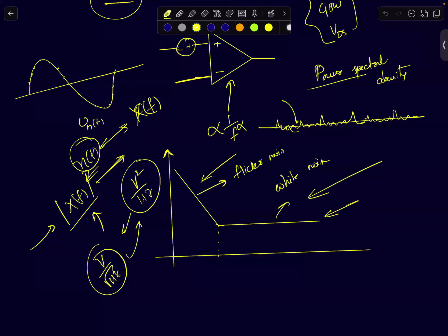In case you guys want, in a different course, we can spend one or two lectures just on noise, how to characterize it and all that. Right now, my goal is not that. I just want to give you the basics about noise and how it is useful for circuit designers. Because at the end, when you are a designer who's going to pick an opamp, you have to choose the opamp with the right noise specifications. If you don't pick the right opamp, then it may fail your application. It may not work as you intended.